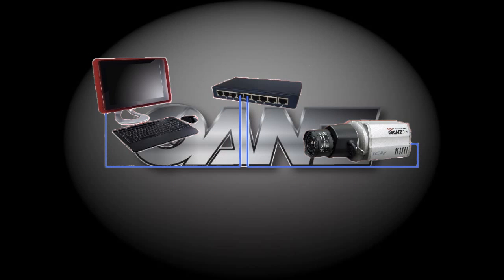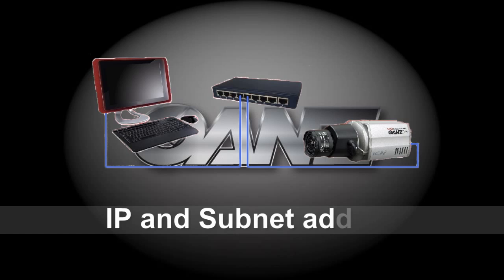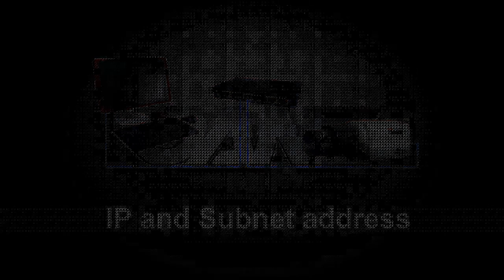Once the PC and the Pixel Pro camera are connected physically, they need to be programmed for communications to happen between them. That means setting the IP and subnet address for both the PC and the camera.